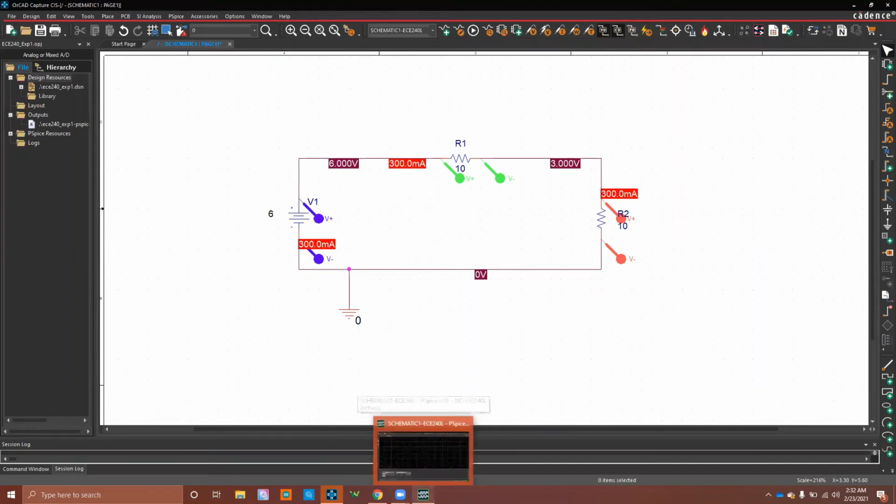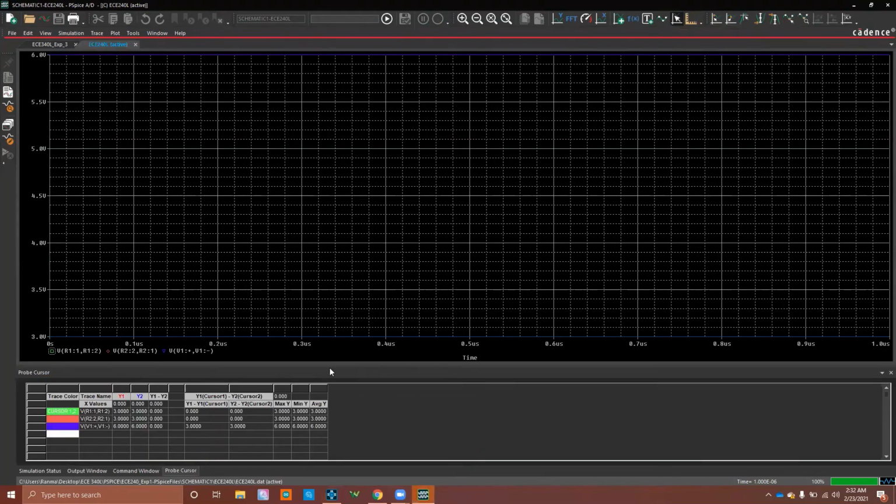I would go back to the simulation window down here and click on this red diamond. Now, when I click on this red diamond and then left click on the simulation, I'm going to get this red line that pretty much acts like a probe and follows that waveform.